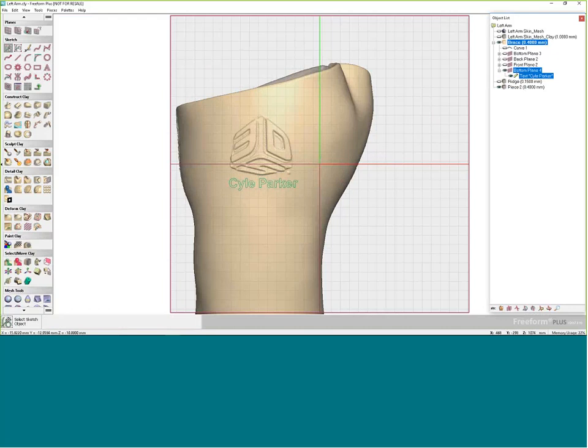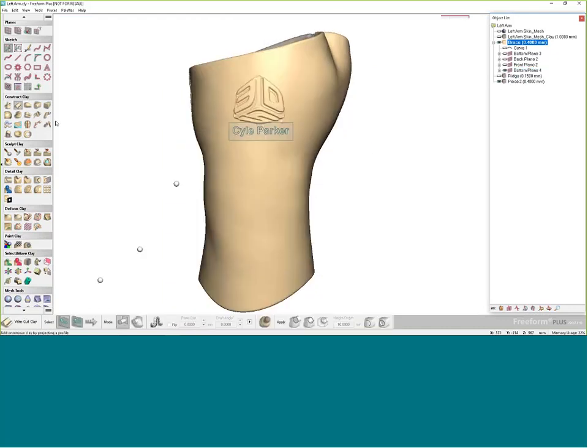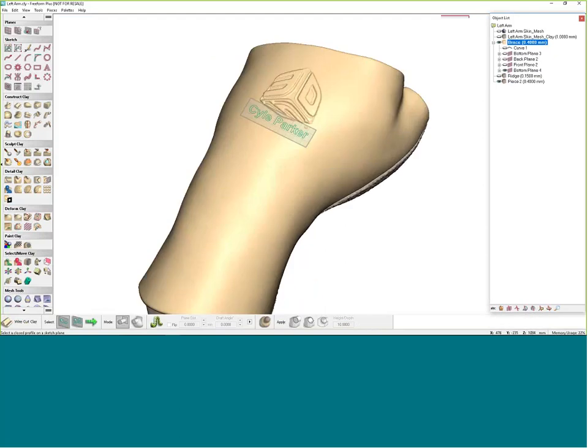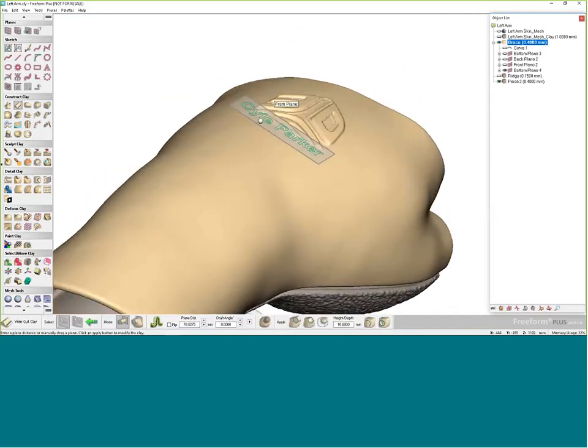And that looks pretty good. I'll shrink that plane down, and then again, I'll use the wire cutting process. So this time, instead of pushing it out or pushing it in, I'm going to use the raise, and it's going to raise this name off of this surface here. I want to do that by probably 1 millimeter is good.